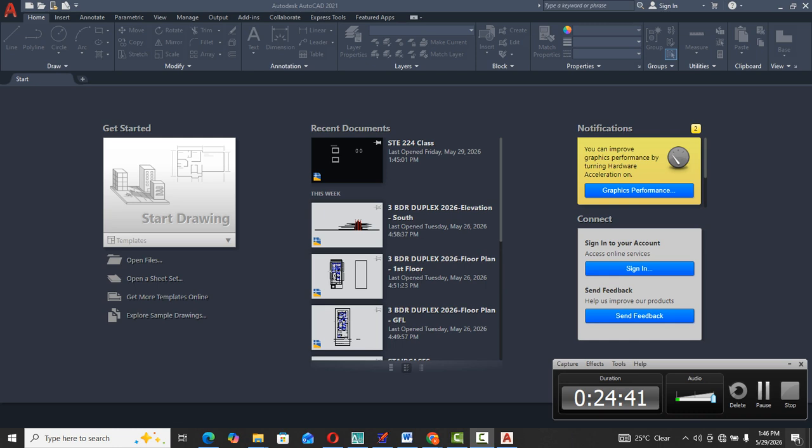Enter. So I select this one as the cutting object, then I say enter. You see that when I say enter, it's now activated for me to trim. So I'll just start trimming as many as I want to. Let me do it again. So trim.